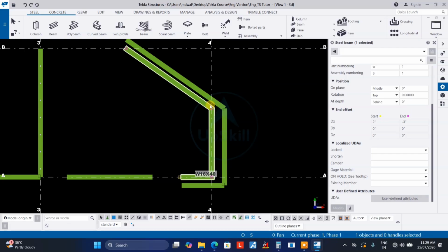So whether we consider the poly beam or we consider the beam, the final decision depends upon the structure and the fabricator. The structure by the load, and the fabricator by the procedure to bend the profile. Whether the fabricator can bend this type of profile or not, we need to discuss and find out. After that we will go for it. This is the concept behind that.